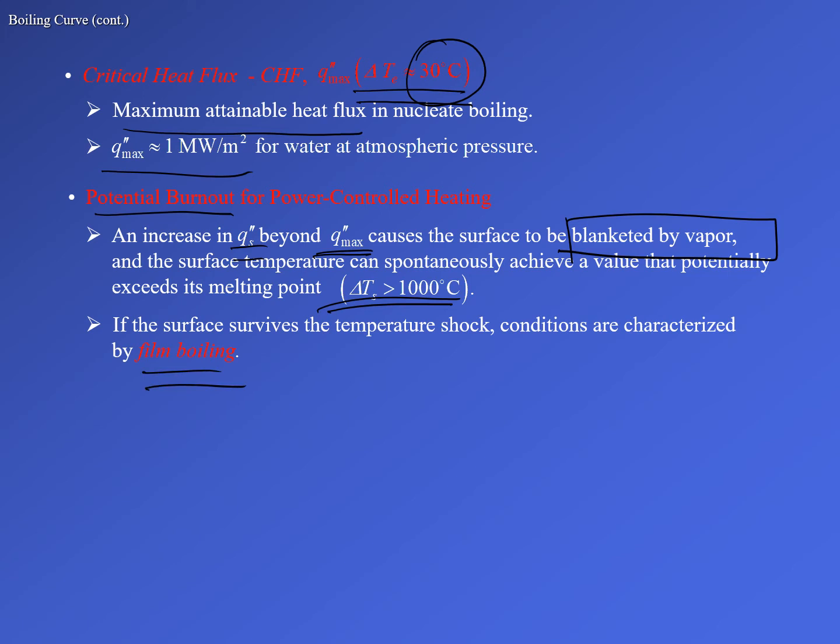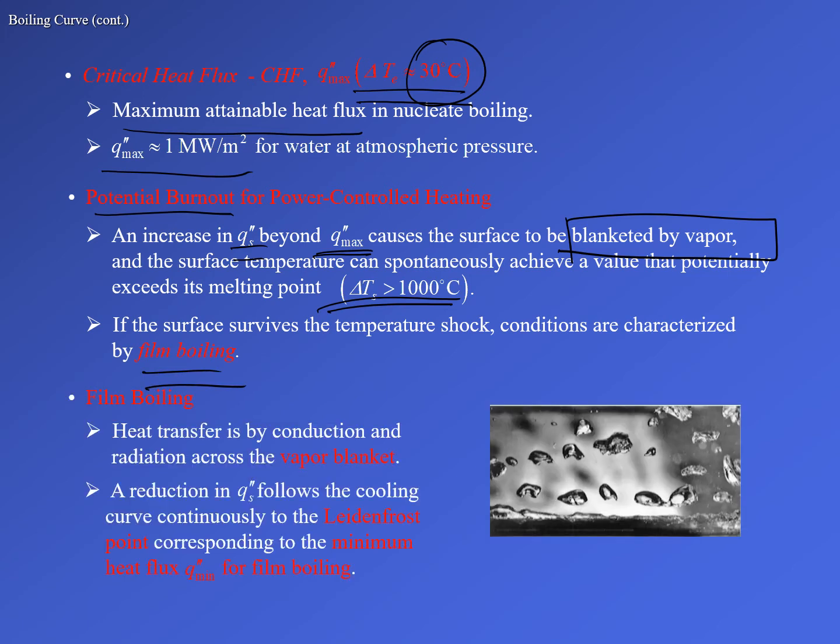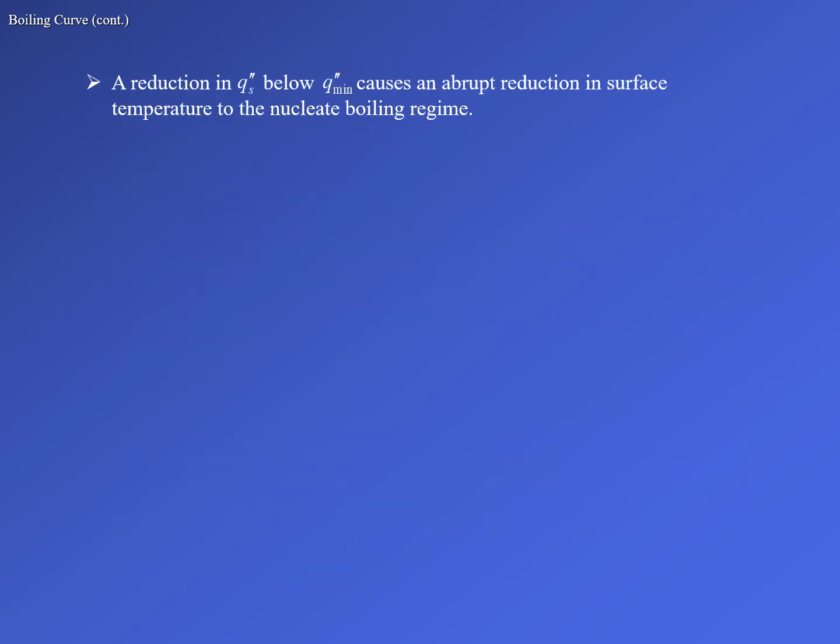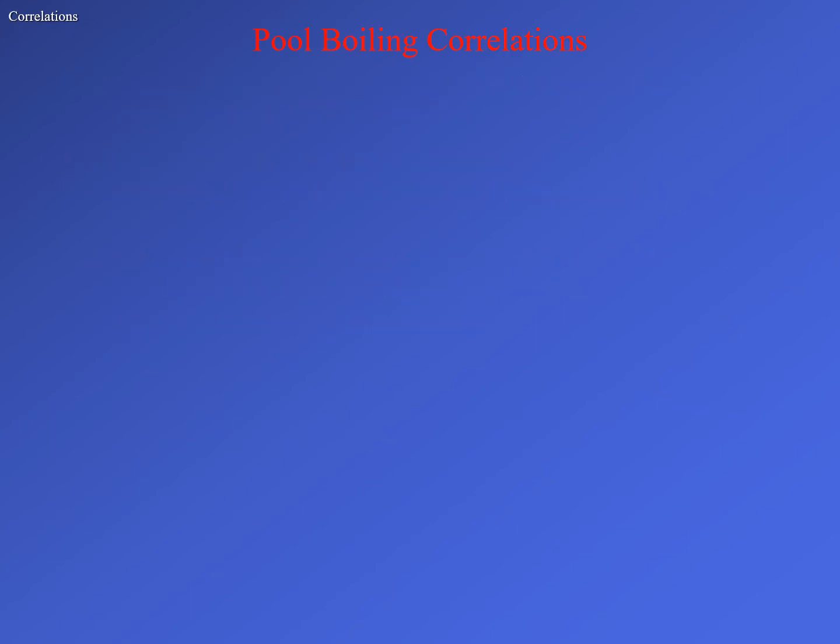And we have a film boiling situation where the surface is covered with vapor. So this film boiling situation has a vapor blanket. As you can see from this figure, you have a vapor blanket here, and the Leidenfrost point is obtained, beyond which the radiation mode of heat transfer starts to dominate. Okay, so I will quickly run through this.